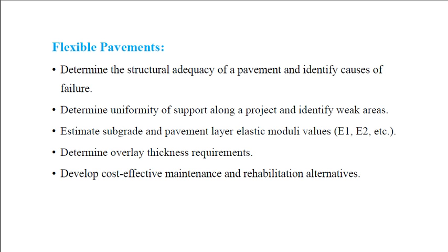Flexible pavements: determine the structural adequacy of the pavement and identify causes of failure. Then determine the uniformity of the support along a project and identify weak areas. Then estimate subgrade and pavement layers elastic moduli values and determine overlay thickness requirements. Then develop cost effective maintenance and rehabilitation alternatives.